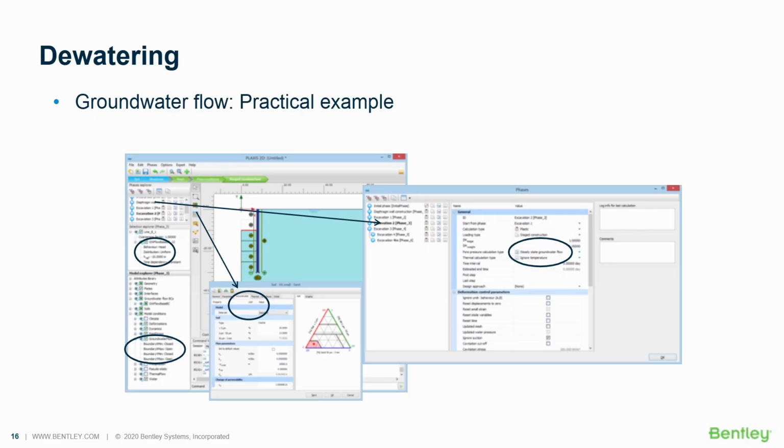And you need to be very careful there, in that by default, Plaxis will always adopt default boundary conditions, which, in my experience, in most cases are not the ones you are willing to consider. Although the default boundary conditions for the mechanical part of the problem are always properly and nicely defined, for flow calculation we are considering that everything is open at the global water level, which is most of the time not what you are interested to consider. So be careful about the boundary conditions as well.